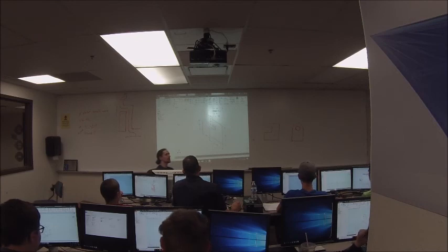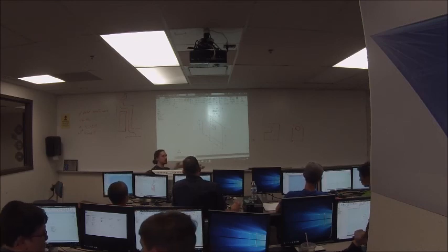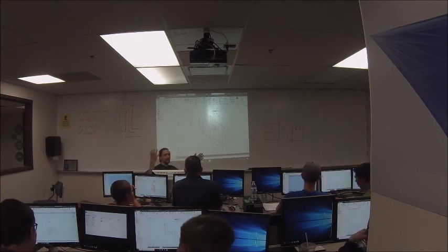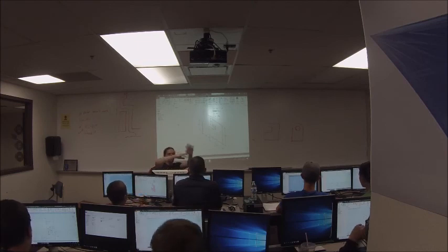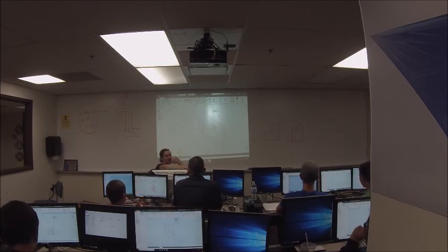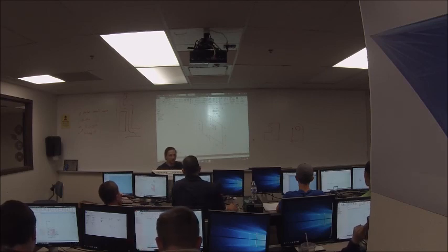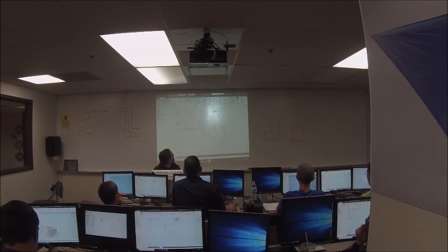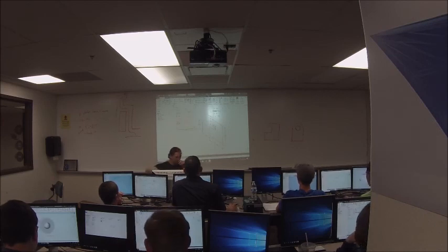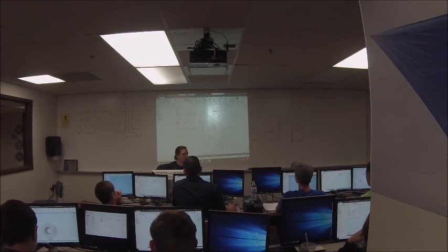Alright, so similar to a sketch, in an extrusion, you just have to pick your regions, say how long you want it to be, and you're done. Okay? For a revolve, you need to pick your regions, specify the axis, and then say how many degrees you want it to revolve. Now by default, in this box here, it'll revolve full, it'll revolve 360 degrees, which in most cases is what you want. It's rare that you want to only revolve part of a way.